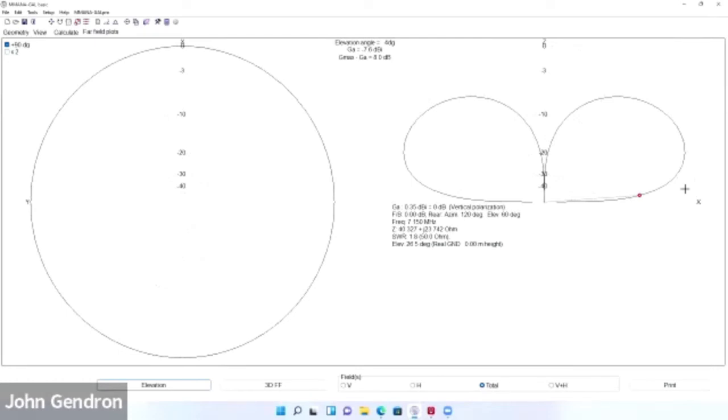And it attenuates when it gets to the atmosphere, because it's not a perfect refraction. The atmosphere is not an eggshell where we're broadcasting inside the eggshell. It's actually more like cotton candy. So some of that RF is going to pass through the atmosphere, and some of it's going to get refracted back.